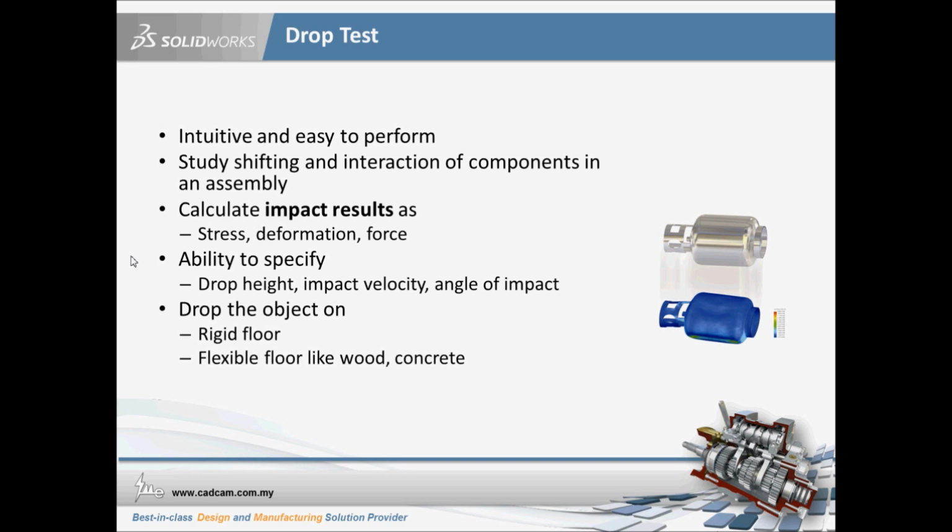Just need to define what materials we're looking at and how high the height of the dropping is. From this simple setup, the software will do the calculation, and from there we will know the impact result in terms of stress, deformations, and force. And the ability to specify is the drop height, the impact velocity, let's say you abuse it by throwing the products, and the angle of impact.